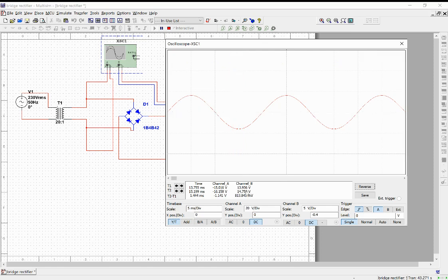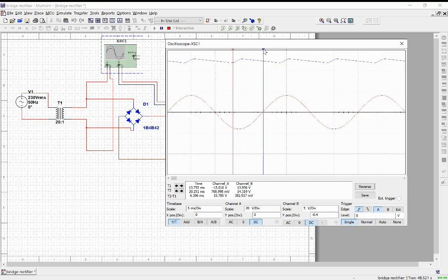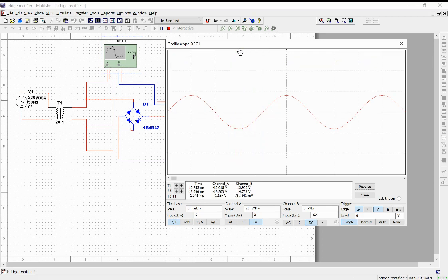The other voltage we're interested in is this peak voltage, channel B. It's the peak ripple, which is 13.9. As we can see, those voltages will change dependent on where we slide our slider to. So ideally you want to get it at the top of the waveform and the bottom, and that will give you a more accurate value for your ripple voltage.